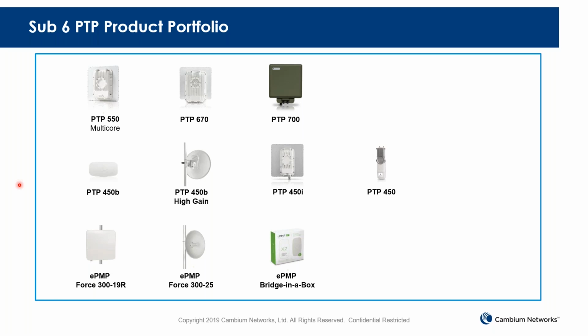The question is really about what is the maximum range. It's a little bit tricky. It depends on which frequency you're using, and more importantly, on the antenna size. The link planner is the best place to go. Literally, you choose your radio. We put all the radios in the link planner. You choose your antenna size. You also need to determine what link availability you're looking for. 4.9 versus 5.9, there's a big difference in range as well.